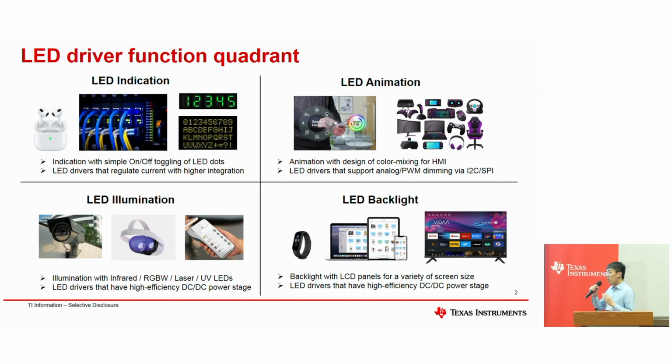Those use the LED driver to output impulse current and do the flashing applications. So from a general standpoint, the illumination LED driver is used for wider applications like infrared, RGBW for color, laser, and even ultraviolet LEDs. And one different thing I want to reiterate is that the LED driver for illumination is generally a high efficiency DC-DC switching, because you have to accommodate different kinds of V-in and V-out power stages.